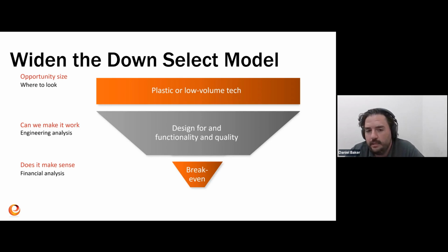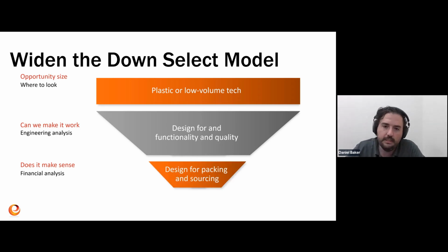can I design this in a different way where I'm not competing with that machined aluminum or that injection molded part, but I'm designing an end use part for additive manufacturing, or I'm consolidating 8 of those components into one. So while a piece part price is higher, I'm reducing 8 pieces out of the BOM. I'm reducing that assembly so that my cost starts to make more sense. And then lastly, we touched on in the beginning in the design guidelines, and I noted it was one of the most important, but can you design for packing and density for manufacturing in your initial design so that they nest well together?